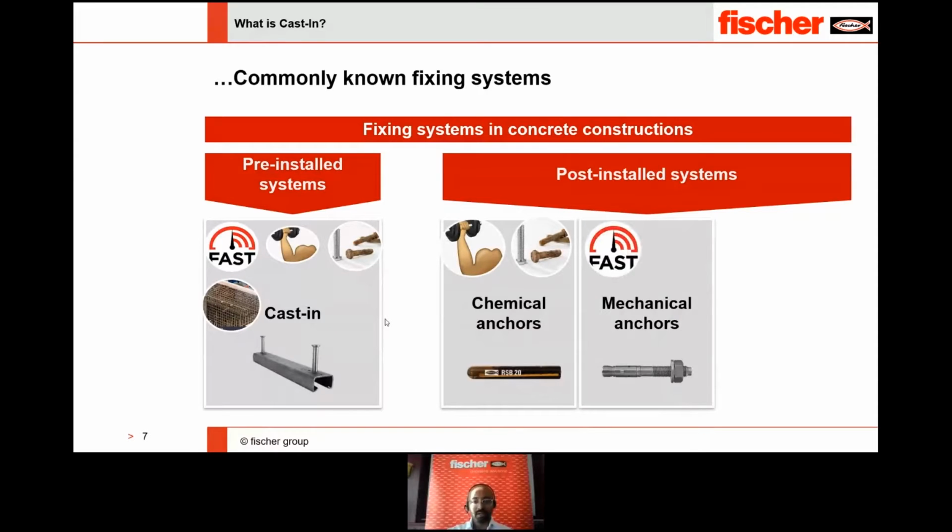You comparatively do not need to wait for a curing time. It is drill, insert, expand, and you can connect. It is relatively fast. And then you can also withstand corrosion, again based on the quality or the type of metal which you choose, it should be adaptable to the environment.